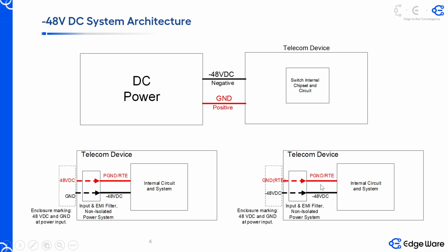Whatever they label, these two device designs are the same. Because if you consider the PE GND connected to the PE of the case, it will be kind of like a positive, right? Inside the circuit is negative. And this is the biggest problem that causes the short circuit in this DC UPS scenario, okay?